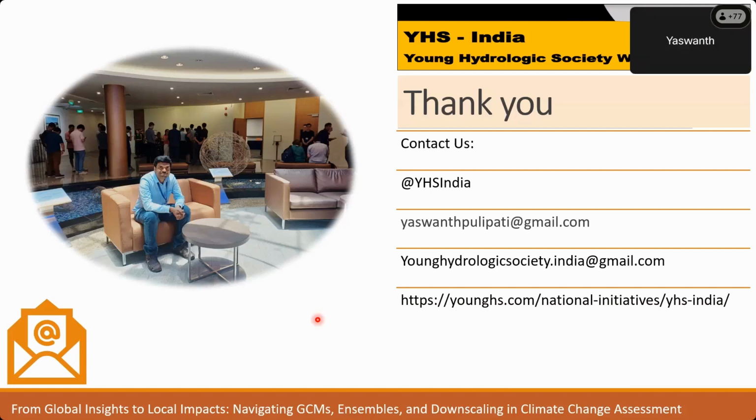So when it comes to downscaling, for example, you have 100-kilometer output from a GCM, and you are running your hydrological model with 25-kilometer input rainfall data. So you want to downscale the coarse resolution GCM to 25 kilometers, which you can do with statistical downscaling or dynamical downscaling. And at 25-kilometer resolution, again, you will compare. That doesn't mean that since you have downscaled, the downscaled data will match exactly with the 25-kilometer observation. Again, the distributional errors will be there. At that stage, when you see the distributional error, then you go for bias correction to match the distribution of the downscaled data with the observations.